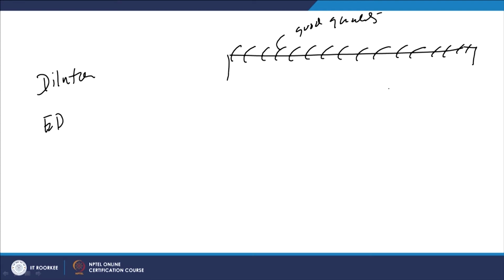The extent of compositional modification of the material which is being applied after the deposition of the bead on plate will depend upon to what depth the base metal has been melted, and that in turn will determine the extent to which change in composition of the material being applied takes place. So, this directly affects the mechanical properties and the quality of the surface layer which is being developed.